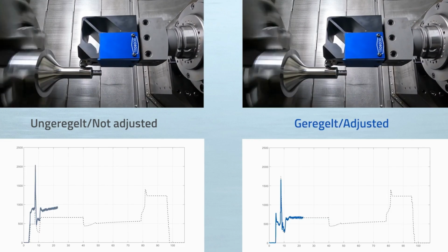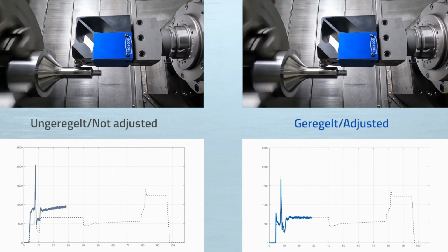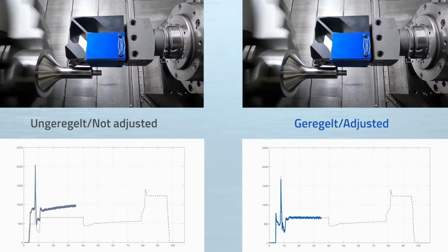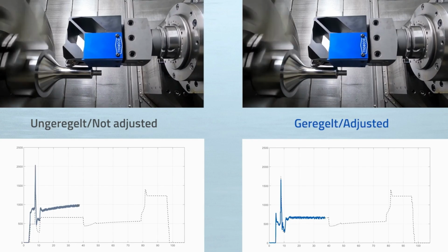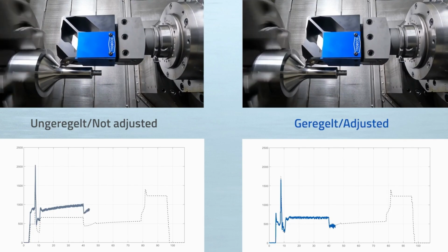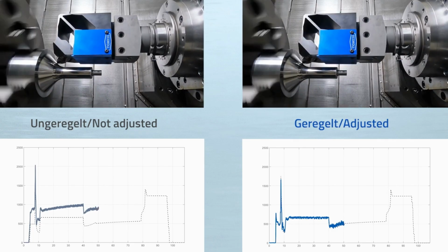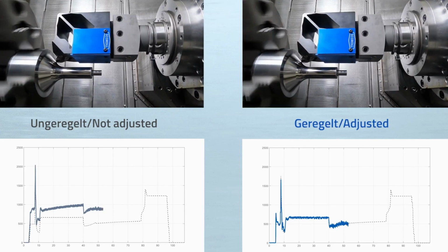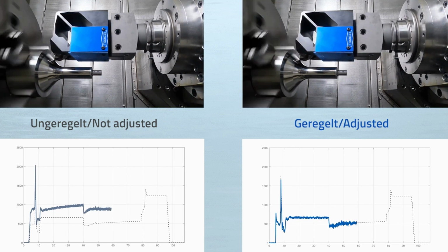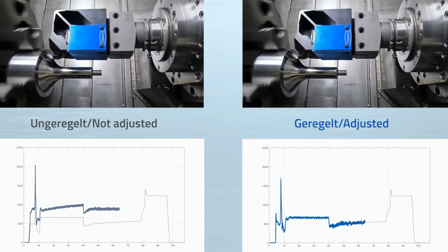And if you follow the graph below, the dashed line basically corresponds to the target specification for how high the force should be. And in blue, so to speak, the corresponding real rolling force as it currently is in the process moves along with it. You can see that without control, we deviate significantly from the process. That might be because the tool isn't ideally calibrated or something, right? But you can see that we're generally further away. And that we especially also have a deformation, an elastic deformation of the component due to its long overhang, which causes the rolling force to vary accordingly. And the closer I get to the clamping, the higher the rolling force becomes, so to speak, if my tool only performs a linear movement, for example.